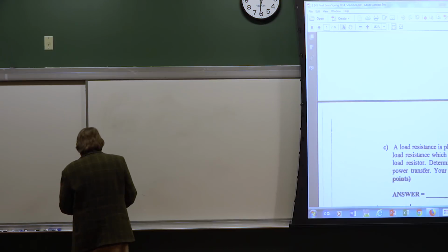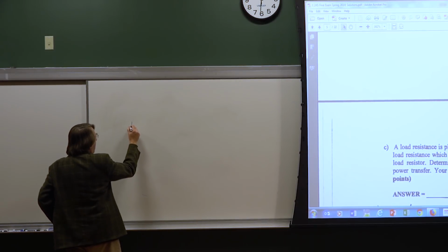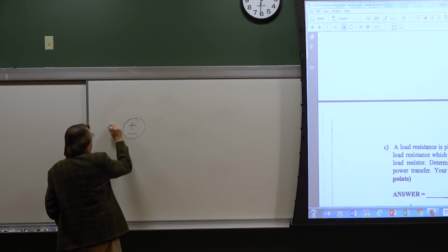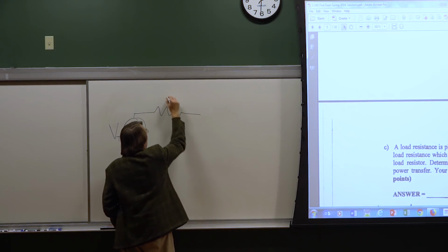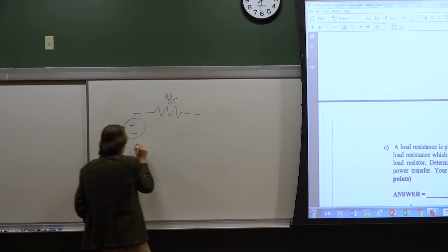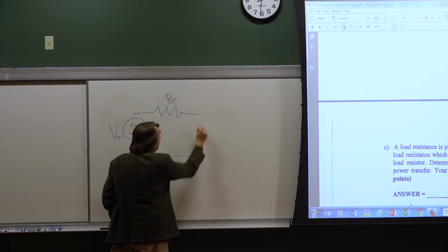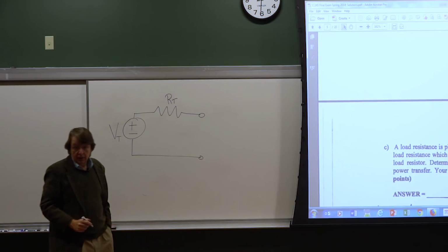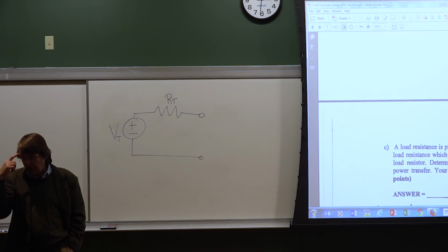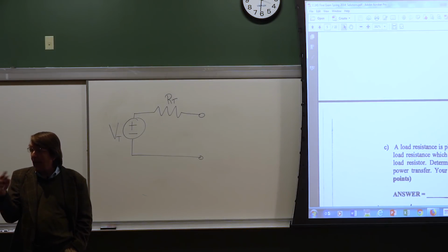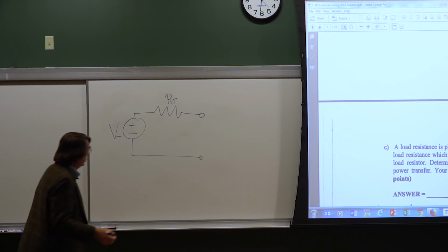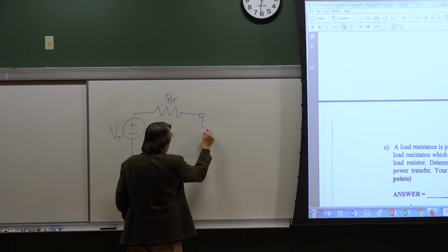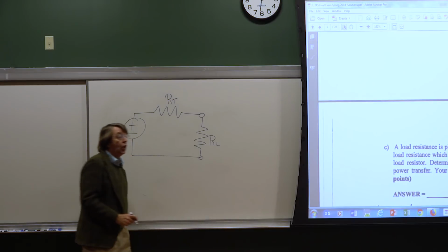Okay. So my colleagues, the whole point behind Thevenin is we're able to replace a complex circuit with a very simple circuit if all we want to do is connect to that circuit. So if I want to just connect to it, I can think of this complex circuit here as nothing more than a voltage source in series with a resistor. And what this question is asking is, you're now going to turn to this amplifier and add an R load.